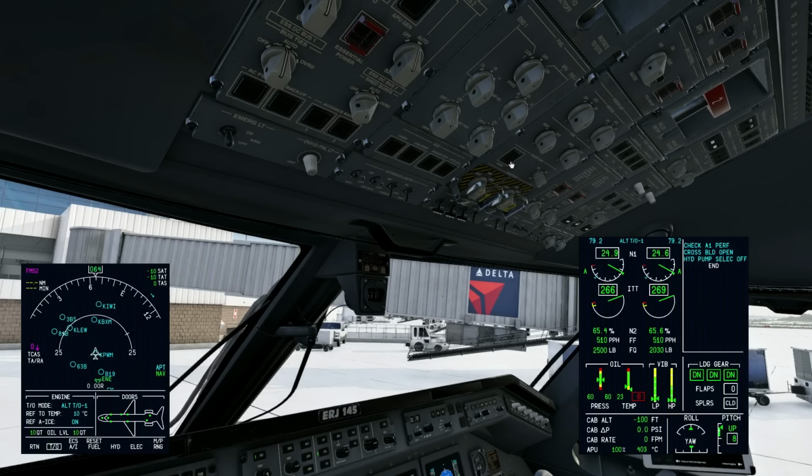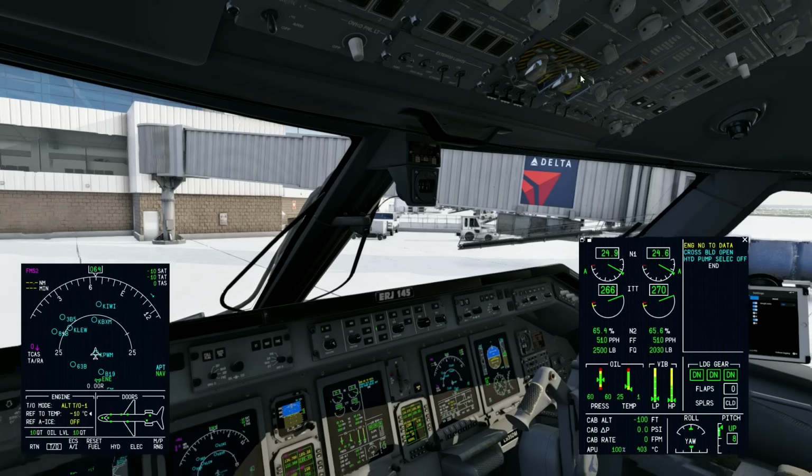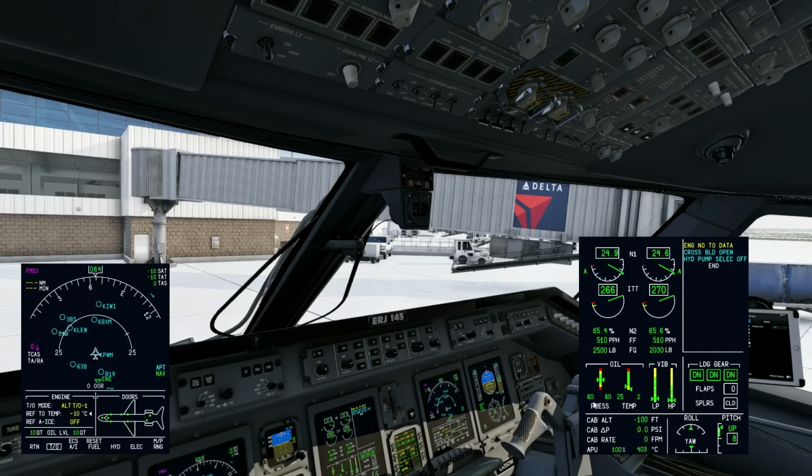I put the wrong temperature in. Should be -10. So, actually, great example here. I deselected, I killed the data by pressing store again, I restarted it, and now I've got an engine with no takeoff data, and I have no data markers. A second ago I had Alt TO1 and data markers. Remember, this engine now doesn't know what its targets are.